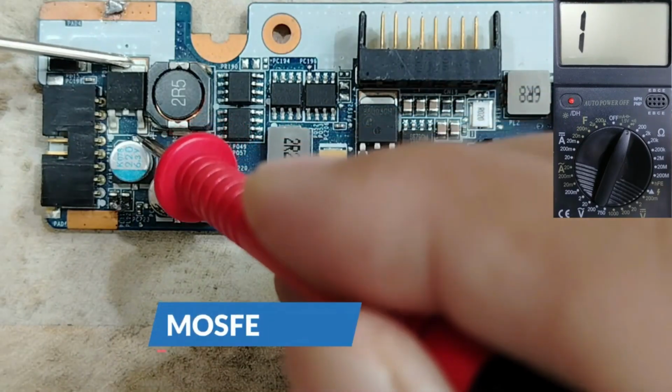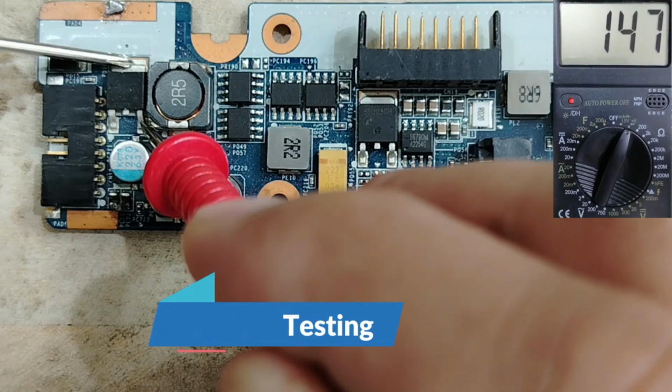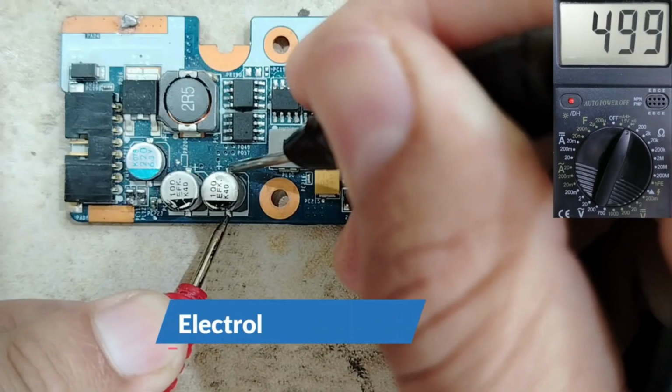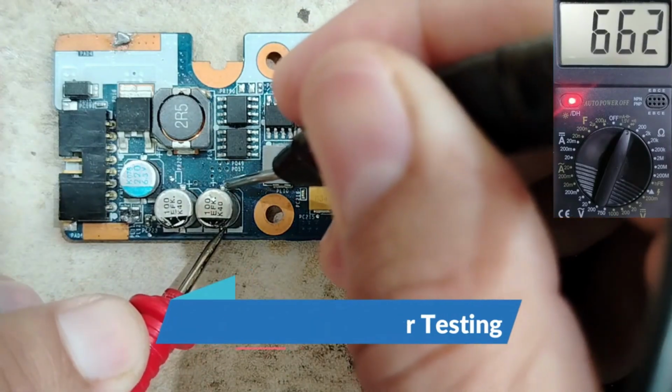Always for the MOSFET between drain and source, you should get a reading, as you can see in the multimeter. Do you see? The capacitor charges and discharges, which means this is a good capacitor.